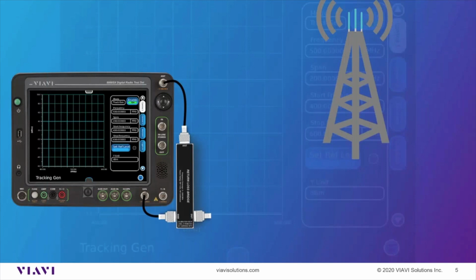And the other thing that we should probably talk about is what VSWR is. That stands for voltage standing wave ratio, and standing waves represent power that is not accepted by the load, or in this case our antenna, and is reflected back down the transmission line. In our public safety two-way systems, everything should be matched to 50 ohm impedance. The cables should be 50 ohms, the transmitter should be 50 ohms, and the antenna should be 50 ohm impedance. So in a perfect world, the transmitted signal would travel down the transmission line and out the antenna.